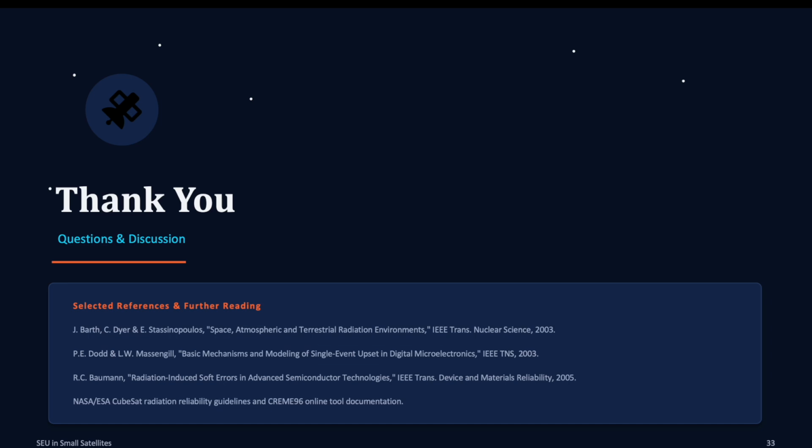If you're operating at low Earth orbit, there's certain expectations that you're going to have more energetic protons, versus if you're going into deep space where you have more heavier ions impacting the satellite. So since the location of where that satellite is going to orbit is a key factor, before you send it into space, the way you implement techniques would be different, and the way you plan for possible failures would be different.